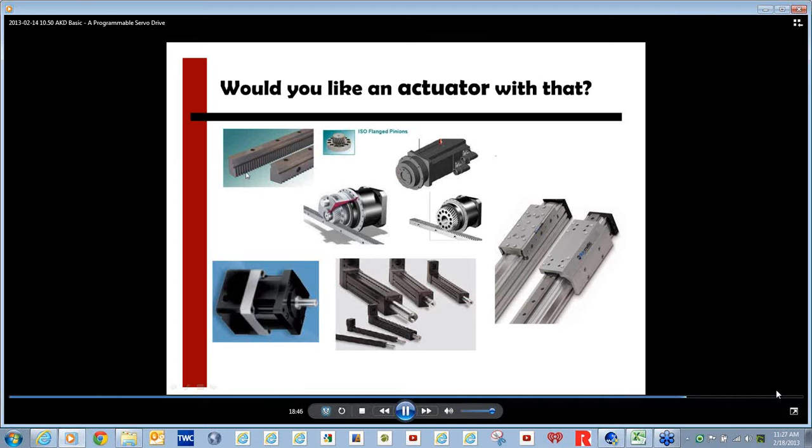These are very precision installation items, though, so being one more item out of the equation really speeds up the assembly time. So if you envision that rack system, and then we have pinions that mount directly on the face of the gear reducer, which will mount right on the face of the motor. And then we have heavy-duty systems available that also include an outbound bearing system to be able to give you some really high thrust capabilities. But maybe something you hadn't seen before on the market.